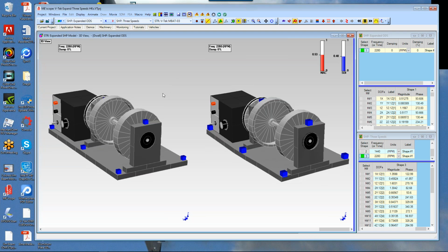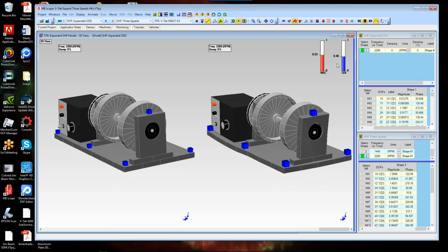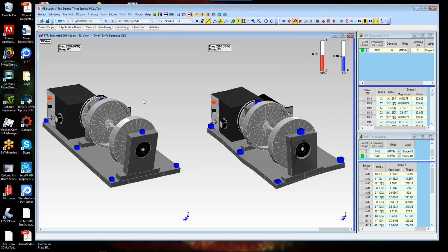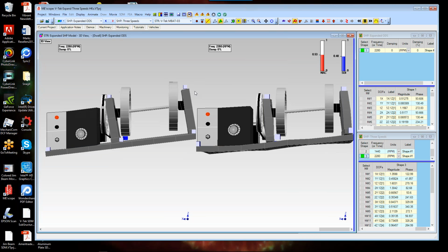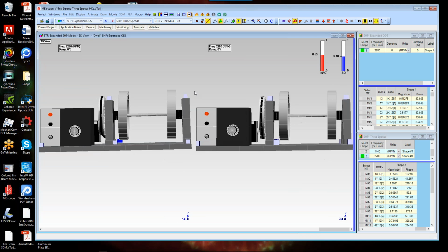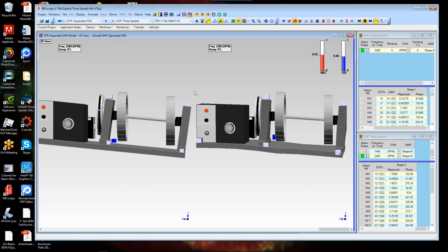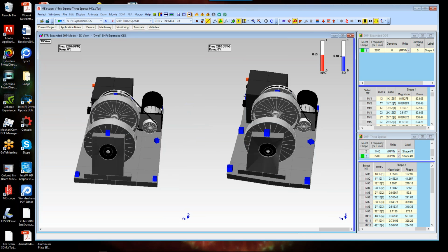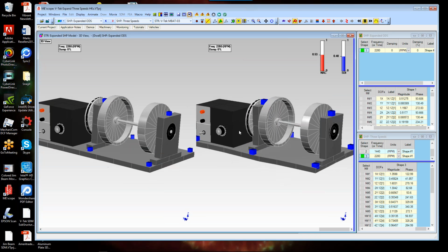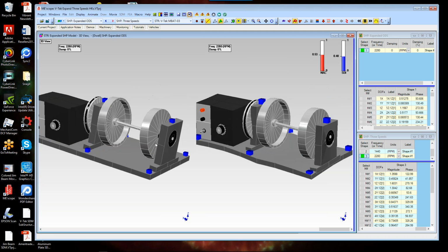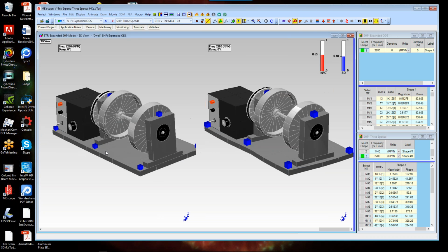You can see that the MAC value in SDI dropped considerably because I'm only curve fitting using the first two modes, the rigid body motion of the base plate and the bearing blocks. So that's not matching up with this experimental data very well because I just don't have a model with enough modes in it.